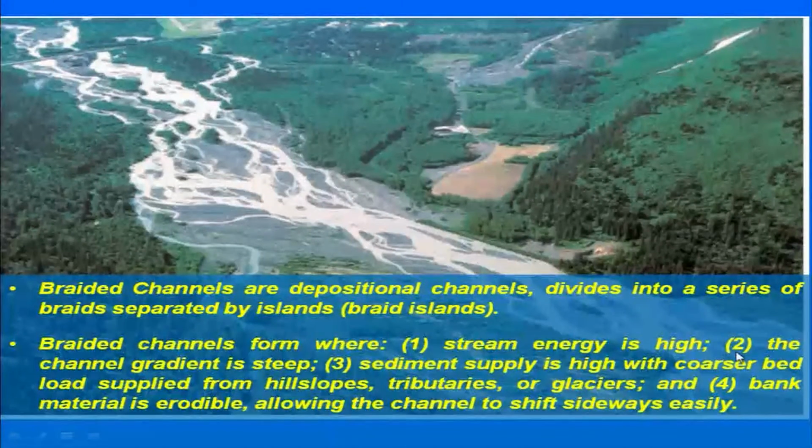So, this is important. The channel gradient is steep. So, you have a steeper gradient, the energy condition is higher, and sediment supply is high with coarser bed load supplied from hill slopes, tributaries or glaciers, and the bank material is erodible, allowing the channel to shift sideways easily.